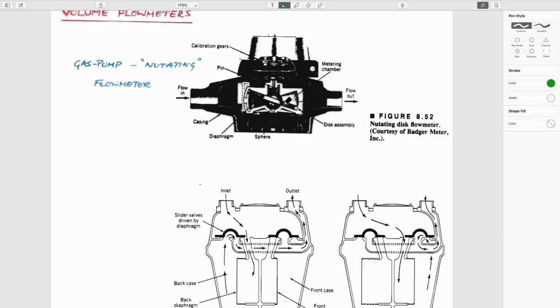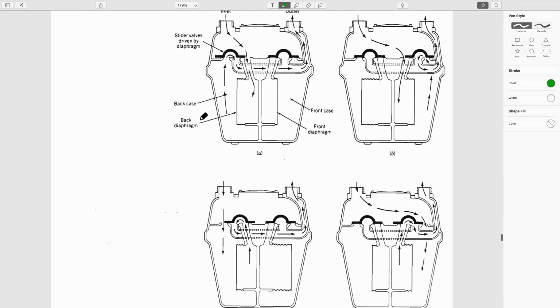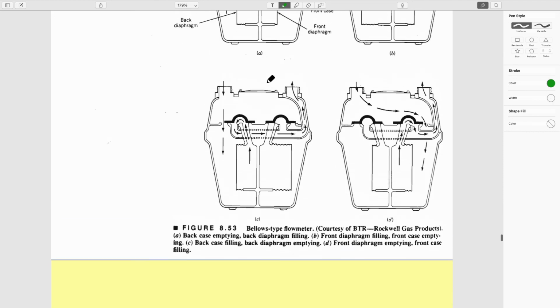it passes it downstream. Gas meters, these big gray boxes that you see outside apartment buildings or terraced houses that are individual units, are based on the idea that it basically takes a volume and it physically acts as bellows to be able to move the volume of a valuable commodity, natural gas. So you measure it quite accurately. As you fill up a bladder, the bladder moves and it exits to a downstream portion, and it just measures it by changing the volume, basically like filling a bucket of water. And so you can measure things in that way.